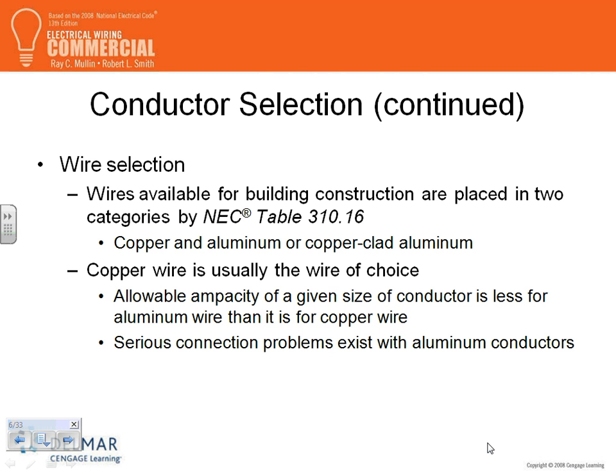If you have a 30 amp circuit, you cannot. If you have a number 10 conductor, you cannot break it for more than 30 amps. And this is only for receptacles and lights. If you have a motor, you can. And I told you guys, motors are an exception.